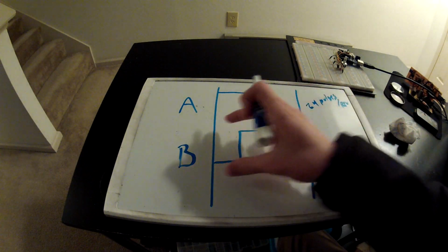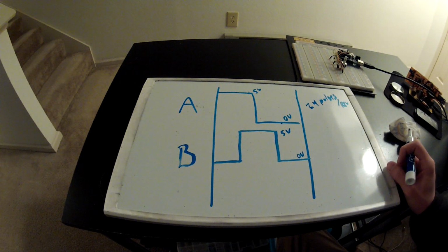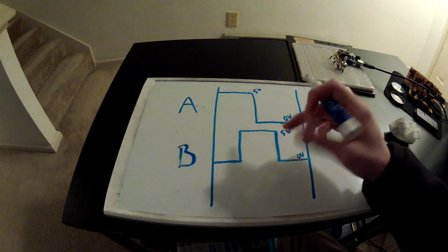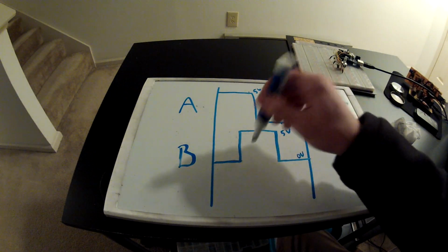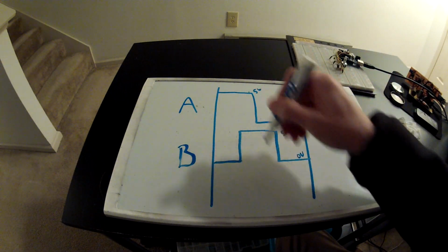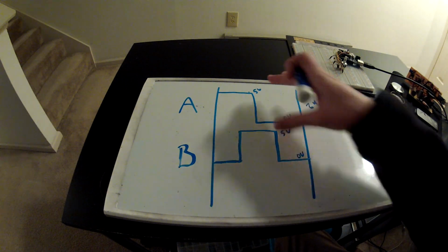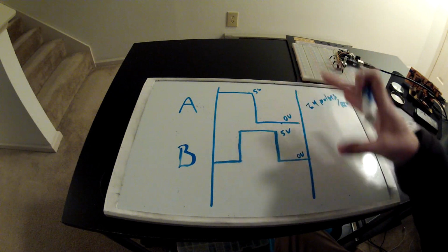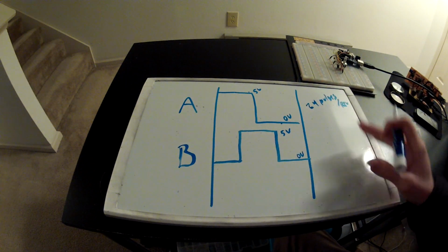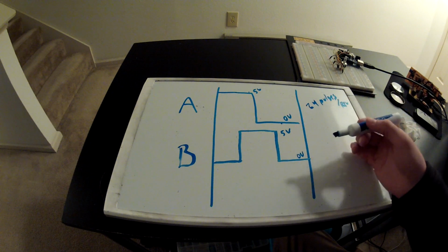It's just a square wave that's exactly 90 degrees out of phase with A. So again, at any point in time, if you measure this B pin or signal with reference to ground, it will be either high or low. But now that we have two of these signals here, we can actually start to figure out which direction we're going in, just based on the trigger events.